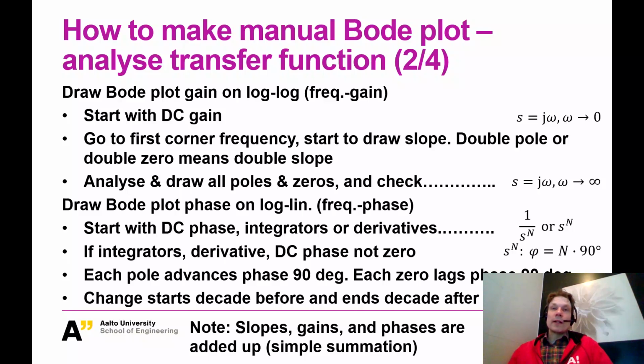And what we have been doing in lecture quizzes, we have analyzed Bode plots in such a way that we have looked at what the DC gain is, so we have put frequency at 0, and then we have increased frequency to infinity and studied the polynomial, what is the limit value it will approach when omega approaches infinity.